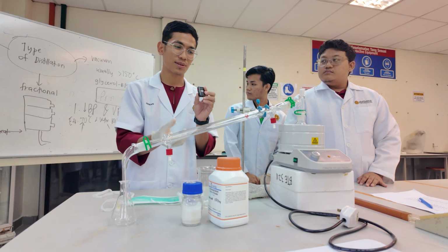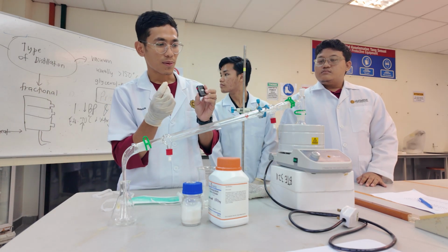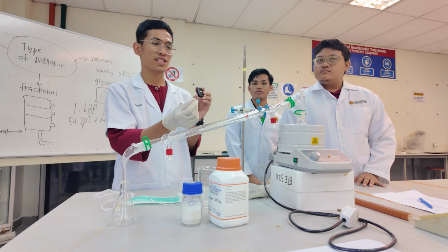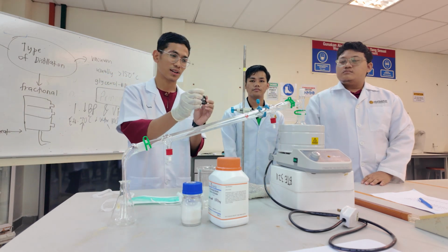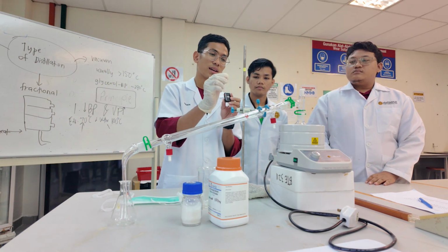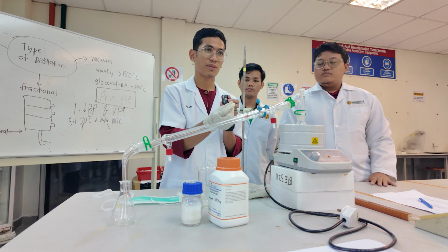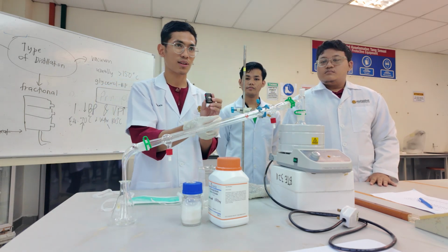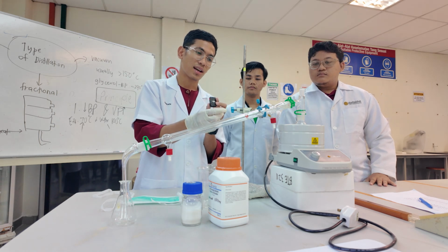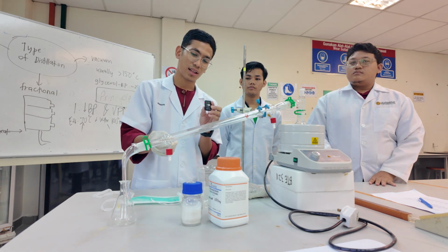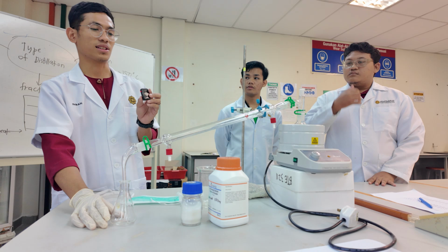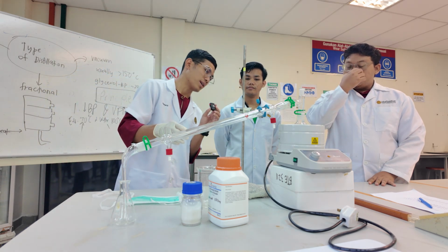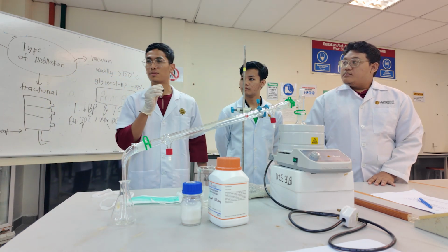How the condenser rolls this phase change is that the condenser removes the latent heat from the vapor, and as the heat is lost, the vapor changes into liquid without a change in temperature. So that's the condensation process.